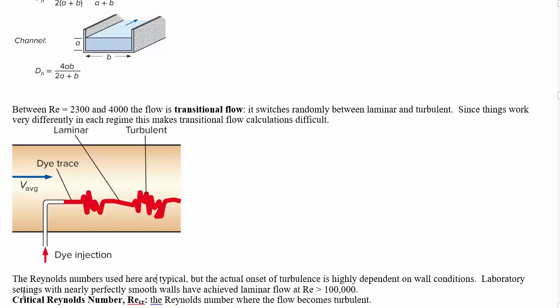It can be below the temperature where it would start to crystallize if there's nowhere in particular that is preferred for crystallization. But any sort of roughness on the wall would be able to kick the whole rest of the pipe into turbulence. It's not that a particularly rough pipe would transition at, say, 2600 and a kind of smooth pipe would transition at 5000. It's more like it's around 4000 for all different kinds of pipes, except possibly super smooth ones in laboratory settings.